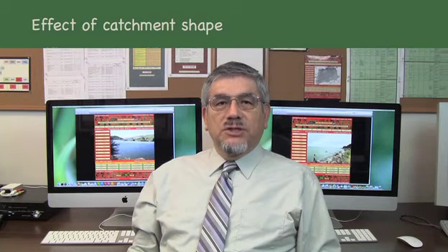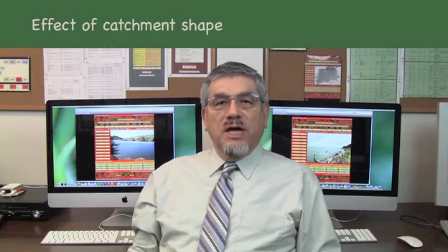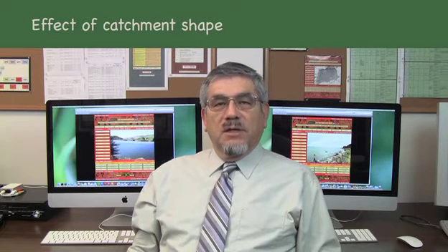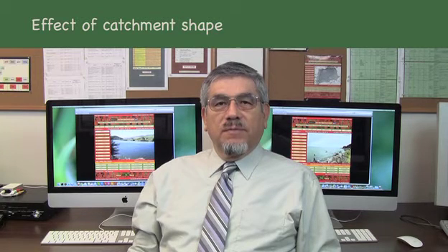The rational method is suited to catchments where drainage area increases more or less linearly with catchment length. If this is not the case, the peak flow may not increase with catchment area. For the peak flow not to decrease in the downstream direction, the drainage area must grow at least as fast as the decrease in rainfall intensity.